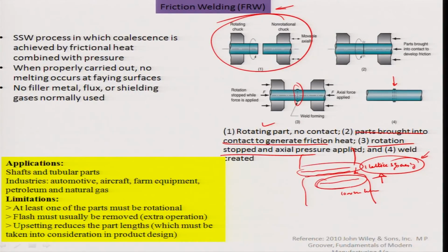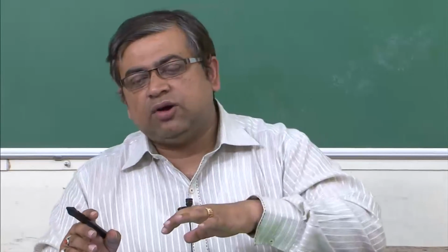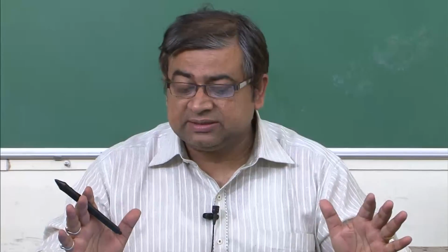So, in this particular case the failure between the sheet metals would depend on either failure across the joint or failure of the material. As in the material there is a crack propagation mechanism which is responsible for failure, this would happen at a much lower ultimate shear strength in comparison to the yield strength of the joint itself. So, the material would fail before the joint. All the principles of solid state welding are based on this fact that you bring the surfaces so close to each other, almost one lattice spacing apart, that the crack formation process, which otherwise is a failure mechanism in the parent material, happens at a lower ultimate yield strength in comparison to the joint yielding as such. So that you must remember is the basic premise behind all the solid state welding processes, and friction welding is also a solid state welding process.